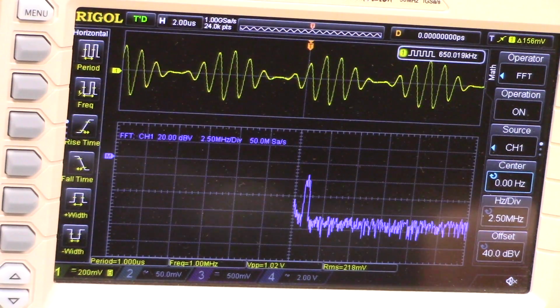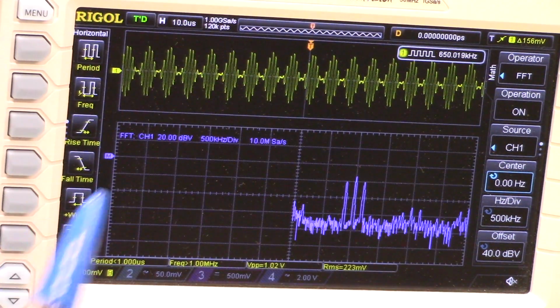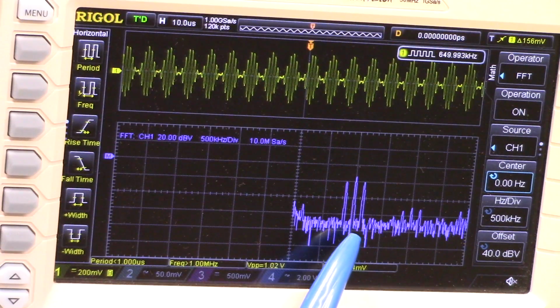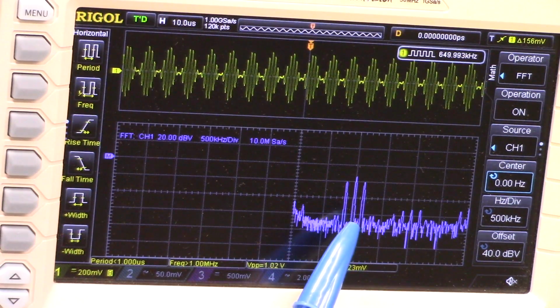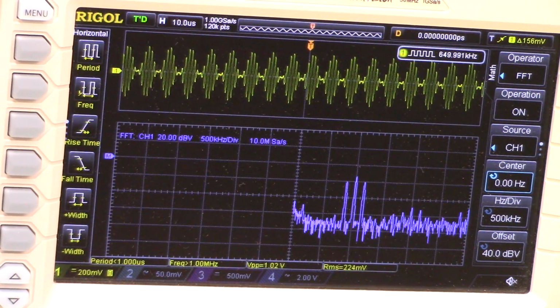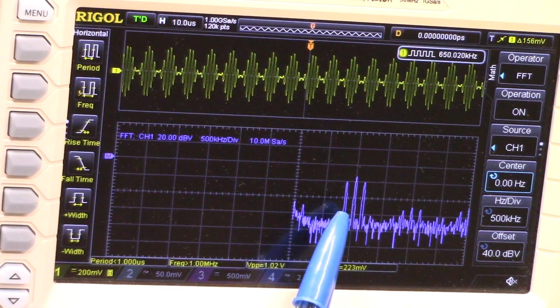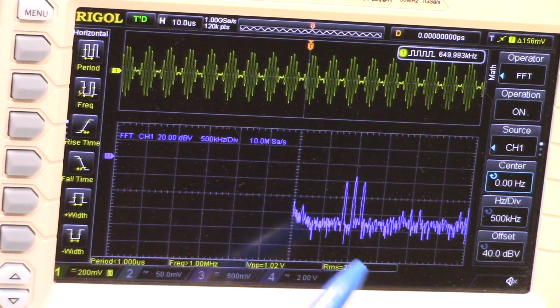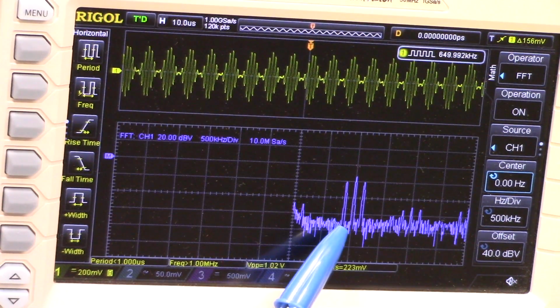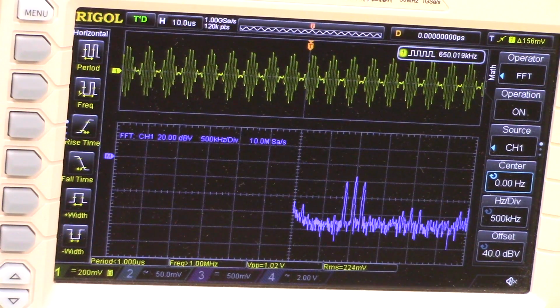From an engineering perspective, when you design a single sideband transmitter, you usually start with an amplitude modulated signal, and then you remove the carrier in some way and one of the sidebands, whichever one that you don't want. There are different ways of doing that. There's with filters, but there are other ways of doing it too, including approaches that involve shifting the phase of the sidebands relative to one another. And there are other approaches as well. Maybe we'll talk about those in a future video.